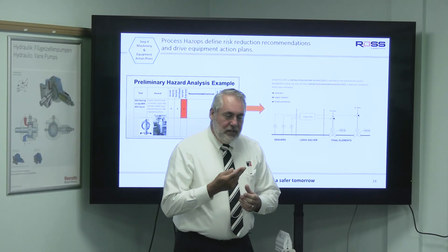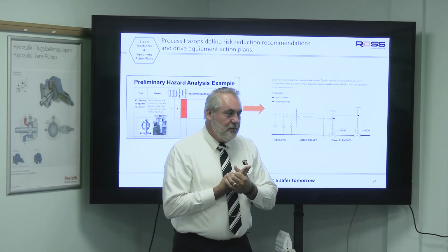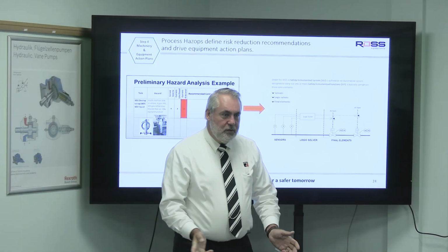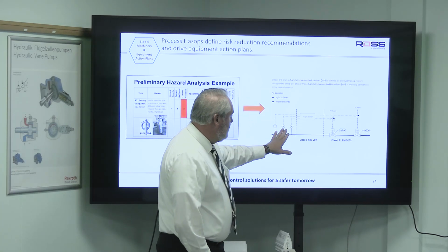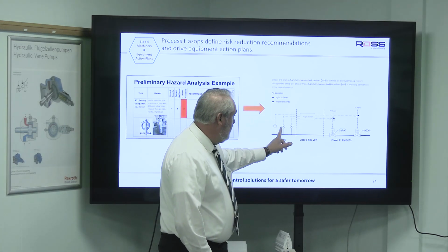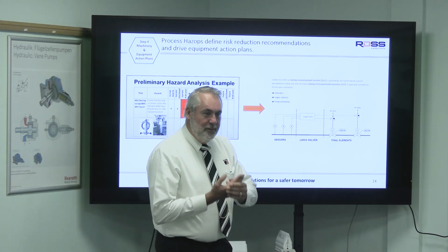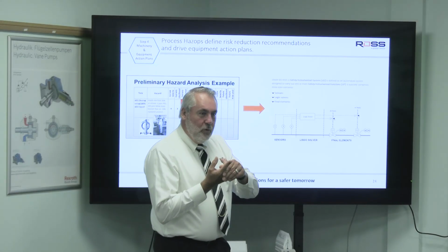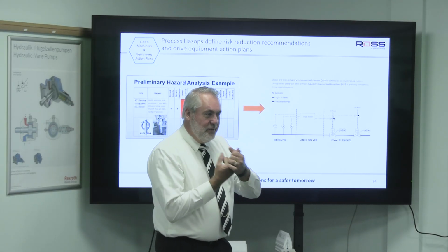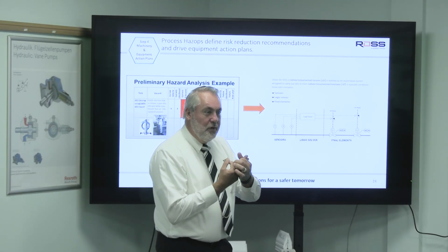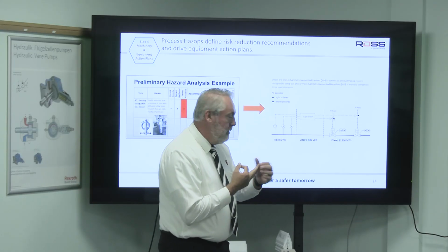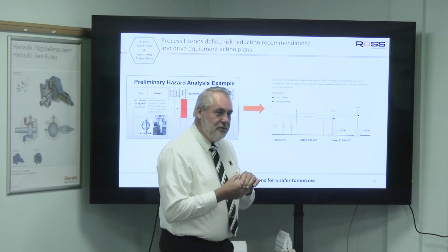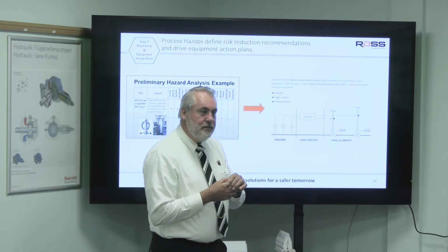So in machine safety, it's usually dual channel systems. If either channel goes off, you shut the machine down. Process world, you want to keep the line running. So what they do is they use a voting system. Okay, I had 1 sensor that went out. Well, 2 sensors are telling me this. I'm going to go with the majority rule, and I'll keep it running, but I'll sound an alarm and say, hey, that sensor's bad. You need to get out there and fix that sensor.